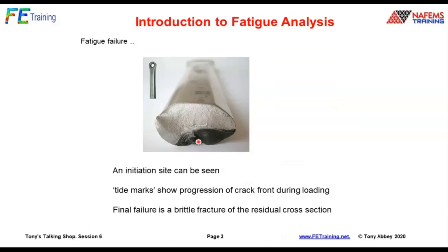From an analytical point of view, fatigue analysis is about finding that initiation point where it's likely to reach that kind of perfect storm. The actual propagation is fracture mechanics, which is a different topic, which I'll probably talk about some other week. And then we reach the edge here, where we just reach an overload situation. So at some point, brittle fracture, fast fracture, and that's a static failure.